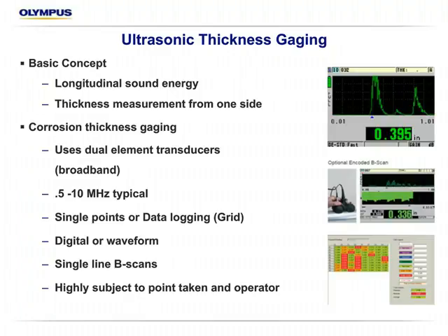But really, a thickness gauge is subject to the point taken by the operator, and there are a few industries right now that are discussing some concern about that. Obviously, if you're given a point to take and that point is difficult to take, it's human nature just to move over a little bit and take another point. So is the sampling really random, and is it really left to the operators? We better have good operators. So there's the general concept.